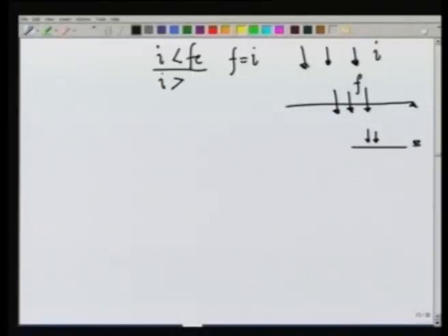As long as the rainfall intensity is less than this, the entire rain can infiltrate. But when the rainfall intensity becomes larger than or equal to Fc, then F will be limited to Fc. So, the rate of infiltration will have its maximum value as Fc, and if the rain is more than that, even then it would be limited to Fc.